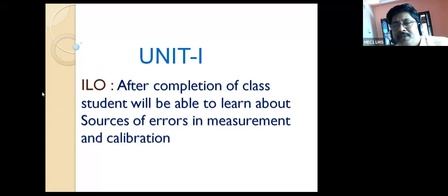So once it is a wrong measurement, then what do we have to do? We know it is wrong compared to the true value. Next step: it's wrong, the output is not equal to the input. Deviation in measurement, right? So what next step? If any instrument is like that, then we have to go for calibration. The instrument has to go for calibration.